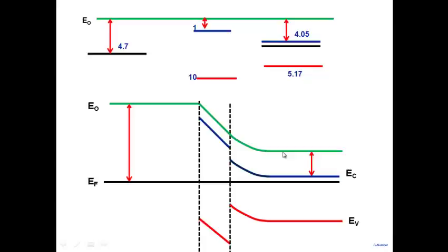Where was the difficulty? In how to handle SiO2. So what we did was we went up to here, and then we said it has to be continuous. We are not bothering about the exact variation. Note that there would be a curvature in this particular part because there are charges here. In the silicon dioxide, there is no charge, so it will go straight, because the slope of E0 gives us the electric field, and the electric field has to be constant. So this will be linear here, while this may not be linear here. So it will go here and join up with this one. Okay, so let's stop here, and please submit the